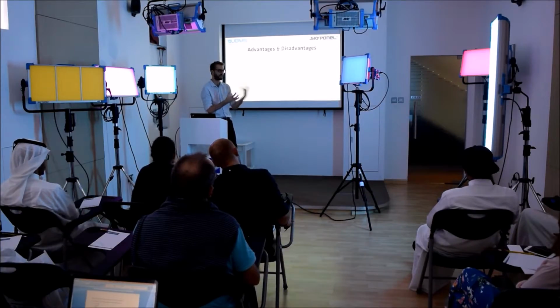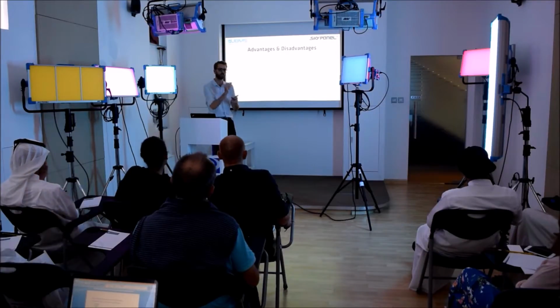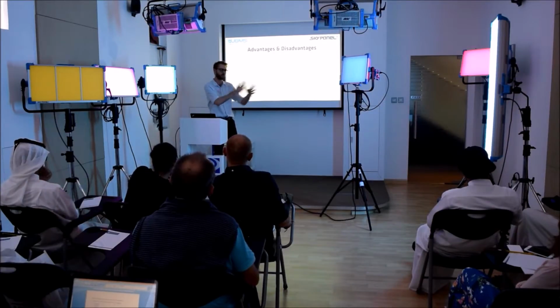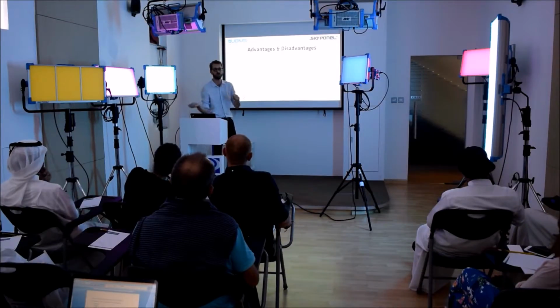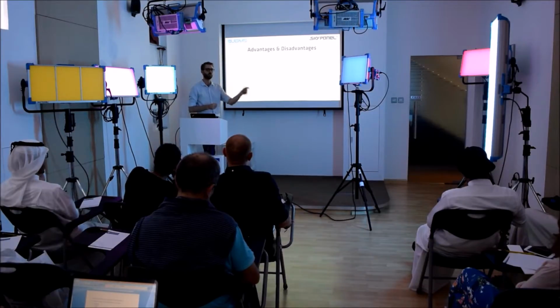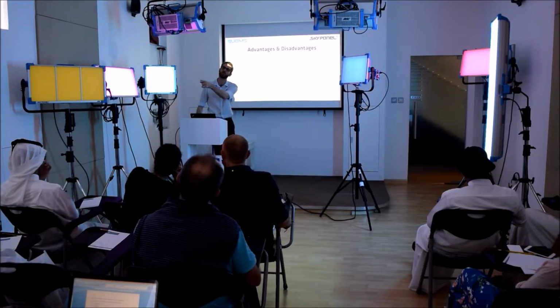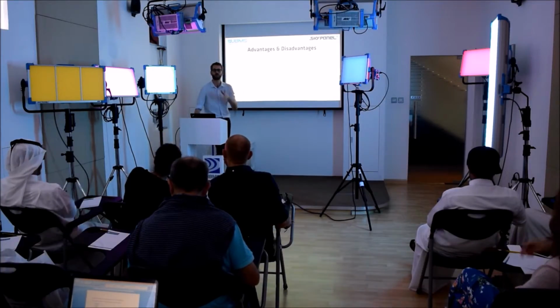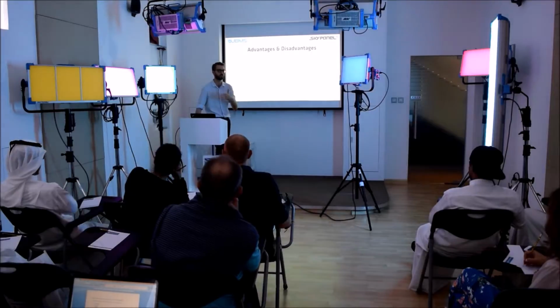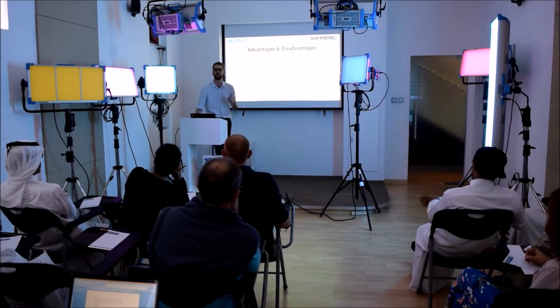But they make red with a very full spectrum red, and green with a very full spectrum green, and blue with a very full spectrum blue. So any one of those LEDs is not the full white, but together they make a very full white spectrum, and they can be tuned to all the colors of the rainbow because they are separated red, green, and blue. Whereas with the remote phosphor, we can't do all those colors because the phosphor panel is just giving us that white light.